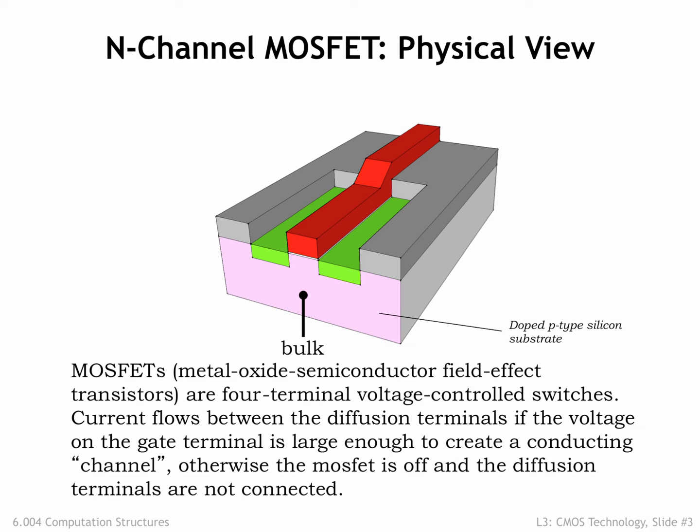voltage. When we want to provide electrical insulation between conducting materials, we'll use a layer of silicon dioxide. Normally the thickness of the insulator isn't terribly important, except for when it's used to isolate the gate of the transistor, shown here in red, from the substrate. The insulating layer in that region is very thin, so that the electrical field from charges on the gate conductor can easily affect the substrate.